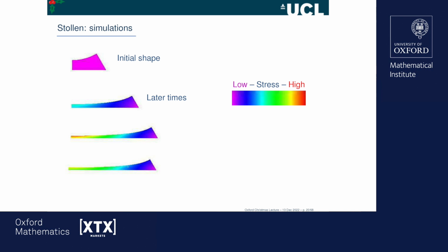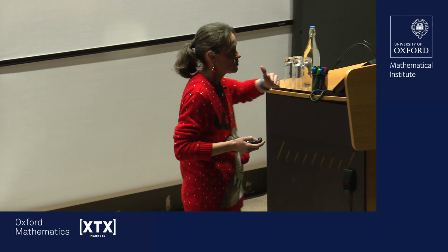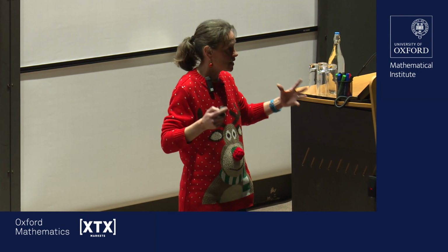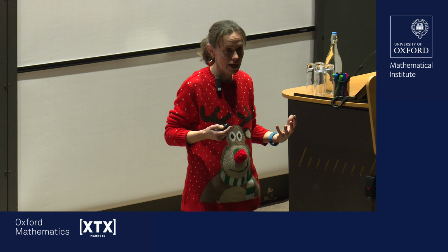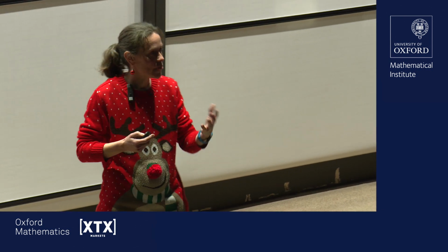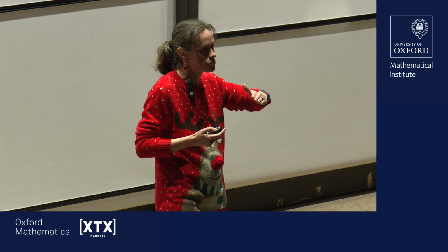what we found was, as we simulate, the initial shape is the pink one, and then as time goes on, what you get is a high stretch in the middle of the bubble face. So that's the thin bit of our simulated thing. And then as the reaction finishes and everything goes solid, that stress relaxes. But that high stress stops the bubbles from expanding as much as they would if it was an ordinary water foam. And you get quite thick walls between the bubbles.